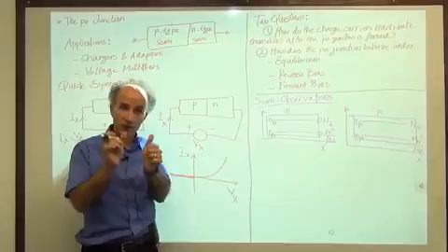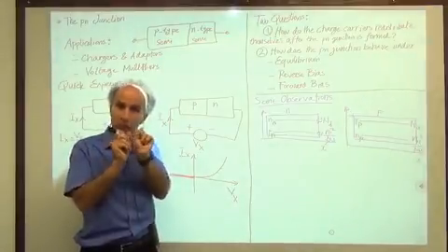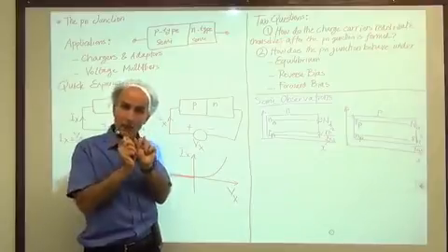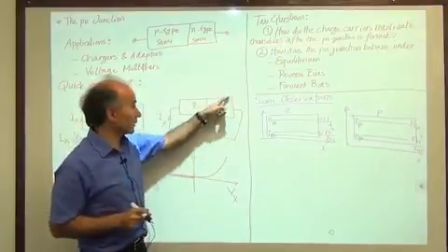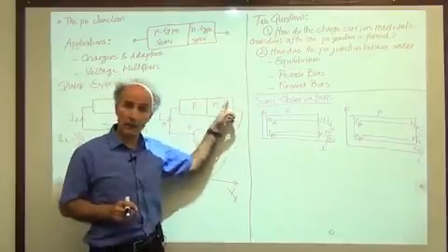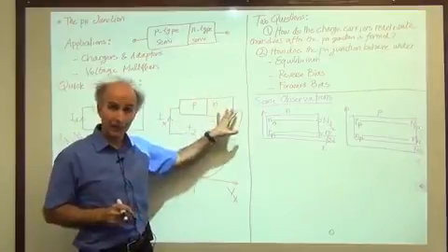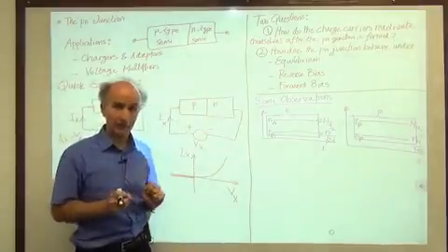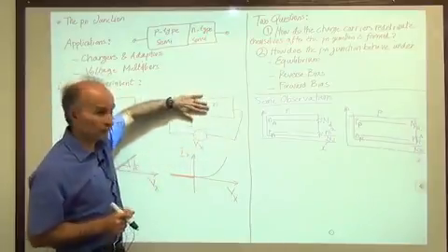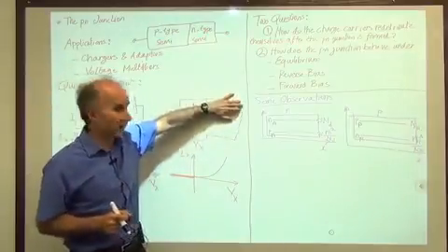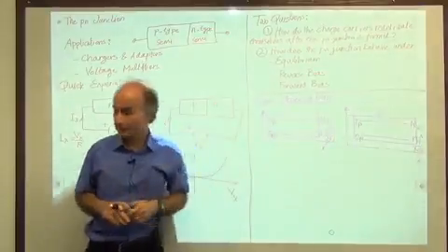And we cannot create a crystal by just attaching or gluing or melting two pieces of p and n together to form a junction. So in reality, we start with one piece of silicon here, and then we dope these differently to create p and n. We cannot just buy them and attach them. But assuming that we have a good crystal here, and we have some p doping on this side, some n doping on this side, we are now ready to study it in detail.